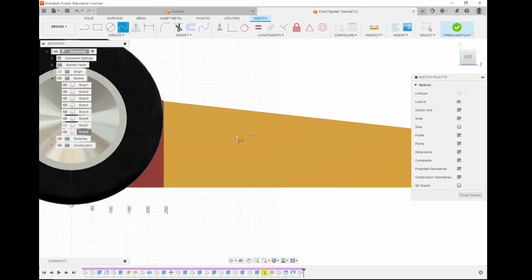Edit sketch. So I press the spline tool, and what the spline tool does is it allows me to make curvy lines. Are you able to see that line better now? Yep. So I'm just pressing it at 2 points over here, and then I press this tick. And so once you do the spline, you see how it has these green dots over here. So since you're in year 12, I can use high technical math terms for you. What this is doing here is it's saying this is a line, so a function, a polynomial of some sort.